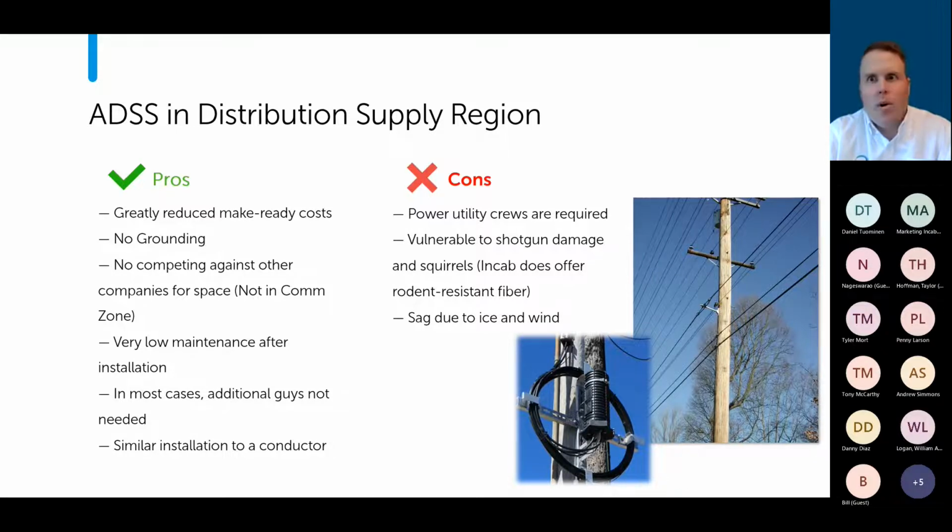If you have 400-foot spans or 1,000-foot spans, you can get a cable that's designed specifically for you, and even dependent on what your pole structure looks like or the size of your poles. Again, if you need to go up above the neutral to help avoid some make ready, you've got a bit more flexibility there. That's really one of the most popular ways for utilities to deploy fiber to the home, by utilizing ADSS.